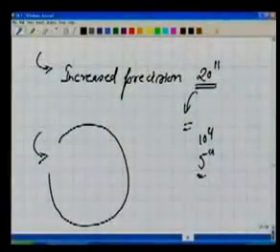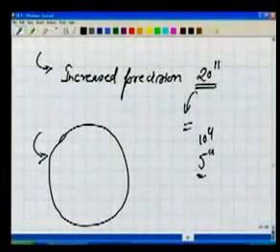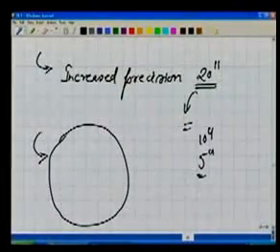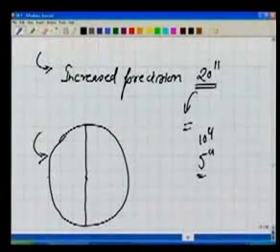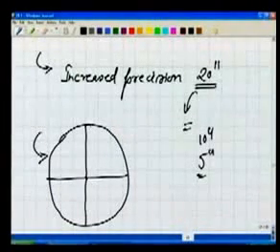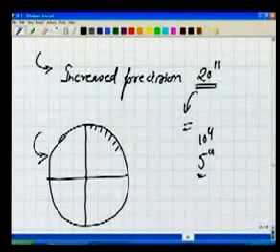But one error, for example, let us say this is our graduated circle, if you are talking of the horizontal one, the lower one. Now ideally speaking, the graduated circle should be graduated in a very uniform way. Uniform means all these graduations should be equally apart.